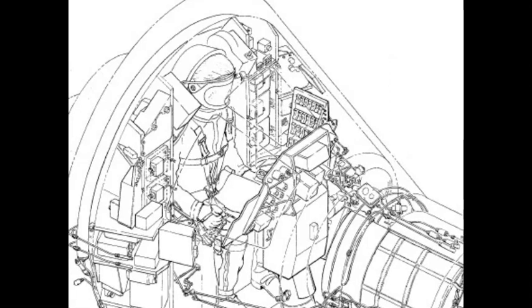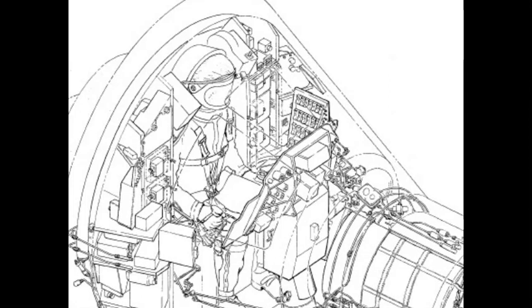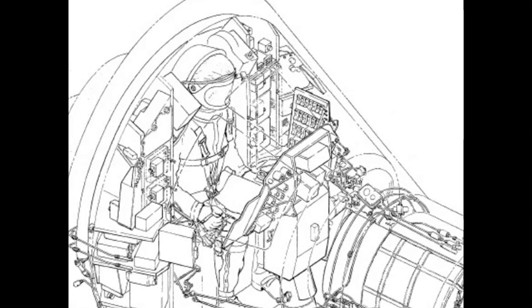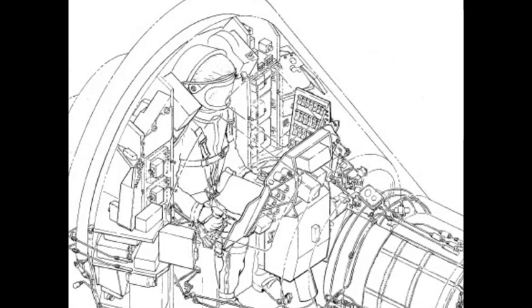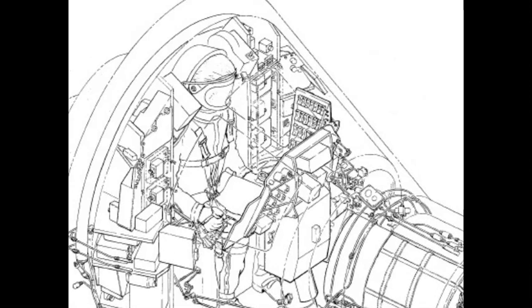The capsule afterbody conical midsection mainly consists of a pressurized cabin that is supported between a small pressure bulkhead and the large pressure bulkhead. The cabin interior wall is lined with channeled frames to provide additional structural strength and equipment attachment points.